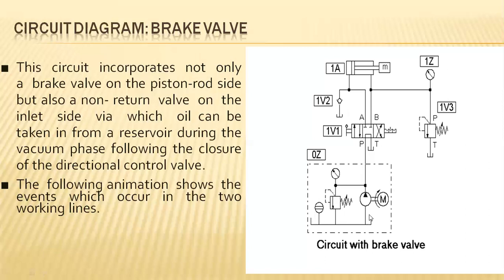Initially this is the oil reservoir of a hydraulic circuit system, which allows or pumps the fluid, and additional pressure will be trapped back by this pressure relief valve to the oil reservoir again. When the plunger is activated in the forward stroke, this position 1 will get into the higher position, and this is the directional control valve which directs the forward stroke or return stroke of the actuator.